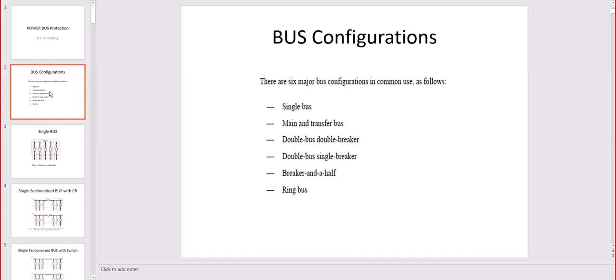For a lower power substation switchyard, sometimes we have the double bus, double breaker. And for the distribution, as I said, either it is a very simple one with a single bus for a small application. Medium voltage distribution typically is breaker and a half. The reason is because it's giving you a lot of flexibility and you can transfer the loads and so on.